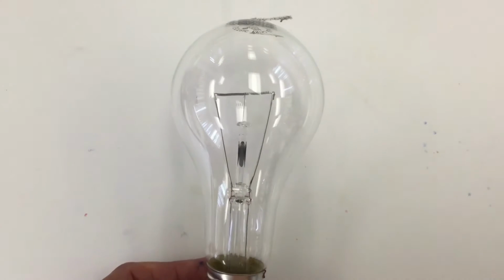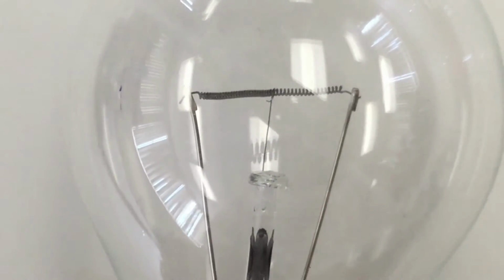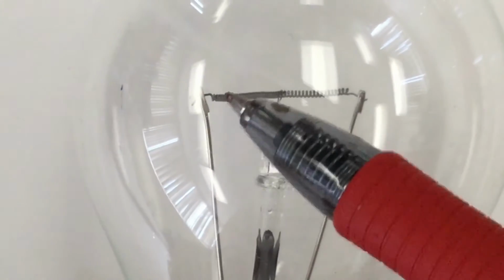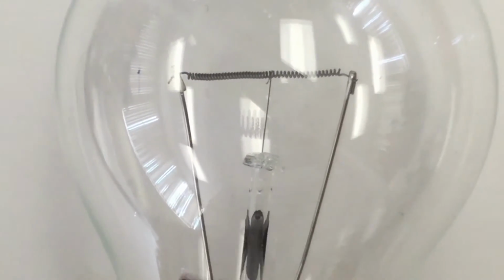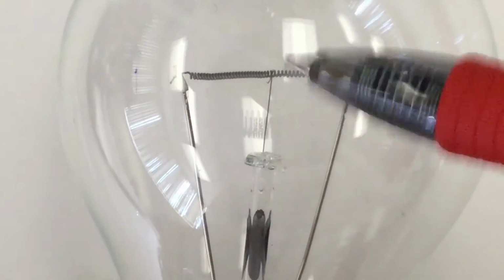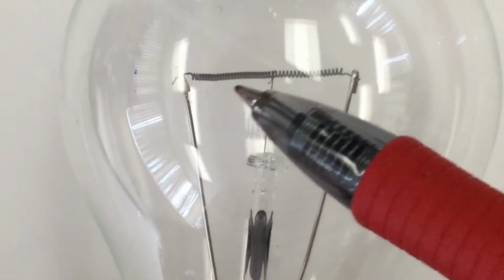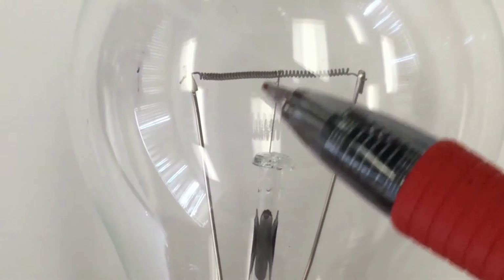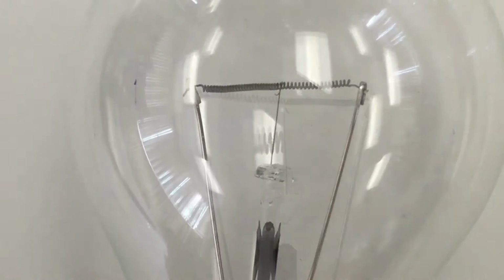So this is a light bulb that works with this filament right here, so it's called a filament lamp. This is a spring that is supported by those two clips. When voltage is applied to those terminals, the current flows through this zigzag spring, and because it takes so many turns, it heats up. The filament gets hot, and then it starts to emit light inside this glass.